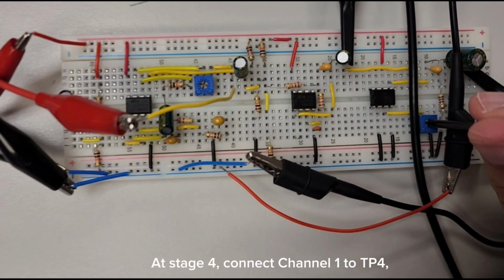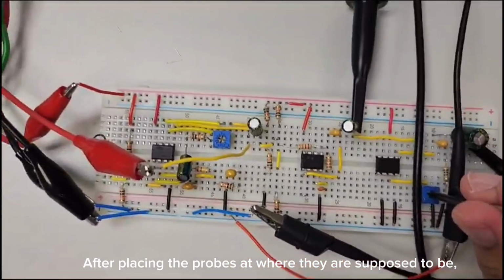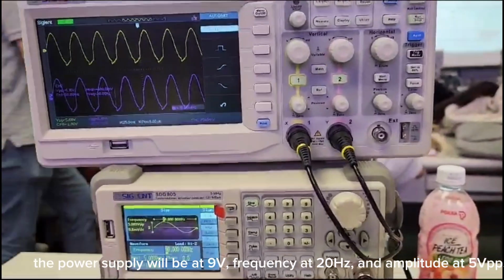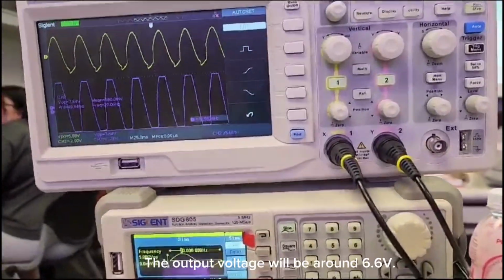At stage 4, connect channel 1 to TP4 and channel 2's probe of the oscilloscope to TP5, leaving everything untouched. After placing the probes where they are supposed to be, the power supply will be at 9 volts, frequency at 20 Hz, and amplitude at 5 volt peak to peak. The output voltage will be around 6.6 volts.